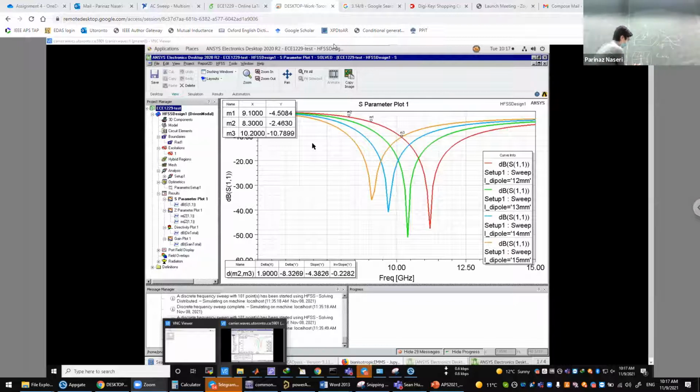Now, if the impedance of this microstrip line or this coaxial line is 50 ohm, which is a standard input impedance for many connectors and cables, you have to design the patch so that the input impedance of the patch would be 50 ohm as well. So somewhere between Z equal to 0 and Z equal to infinite, the input impedance becomes 50 ohm. Okay, so that's why we don't feed the patch right at the edge or right in the middle. We feed it somewhere between these two.